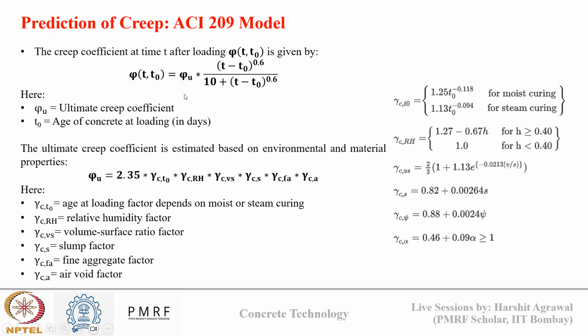It is based on ultimate creep coefficient, which takes into account different material properties like age of loading, relative humidity, volume to surface area ratio, slump factor, fine aggregate ratio, and air void content.